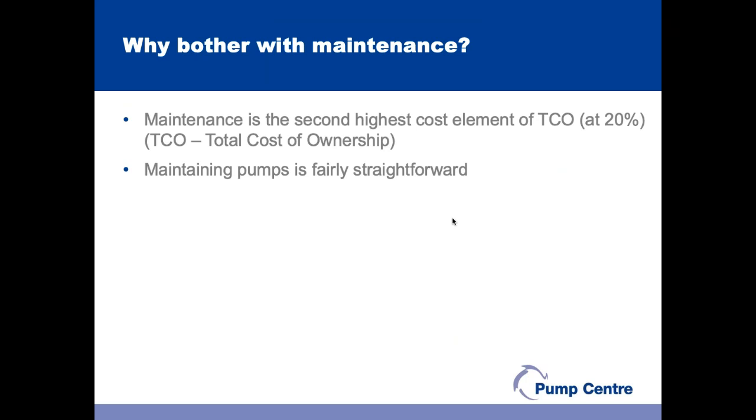Now, depending on who you talk to, the cost of maintenance in terms of a total cost of ownership situation varies, and it clearly varies between different types of pumps and between clean water and dirty water. It could be 5%. It's typically about 20% on dirty water pumps.